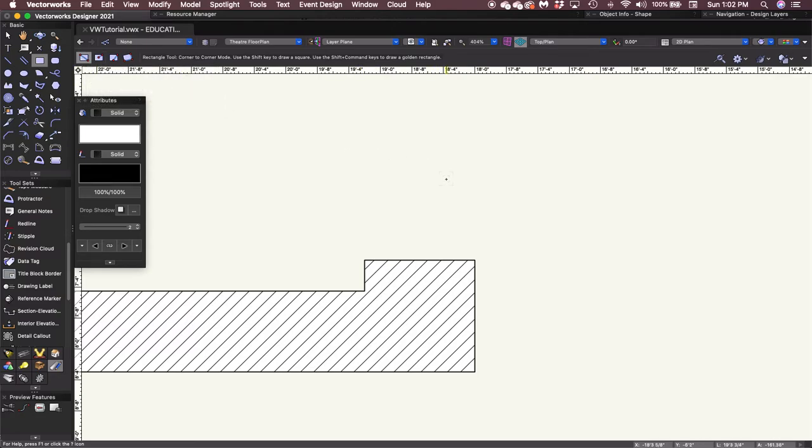Okay, so in creating our smoke pocket, I'm going to start at the upper right hand corner of the proscenium, and I'll click once, and now you can see I'm drawing from corner to corner, and I can make this rectangle various sizes, but I still have my floating display bar, and that's how I'm going to edit this right now.